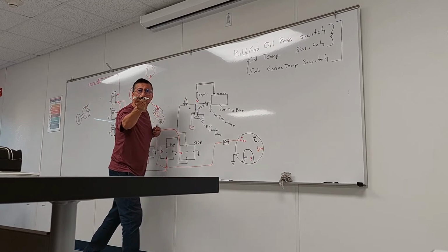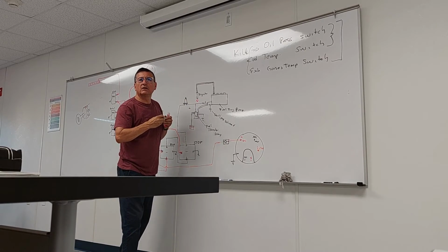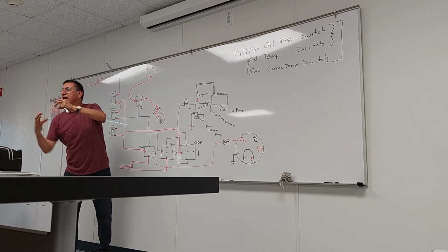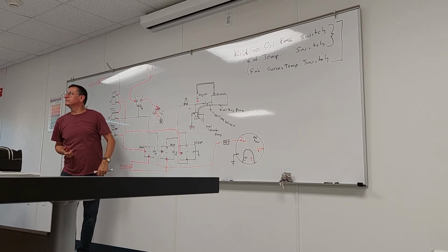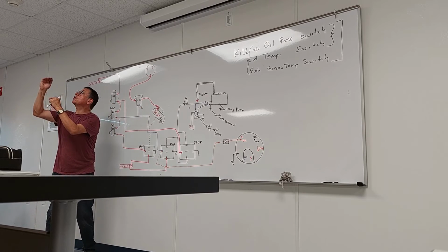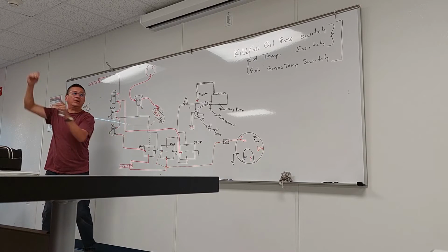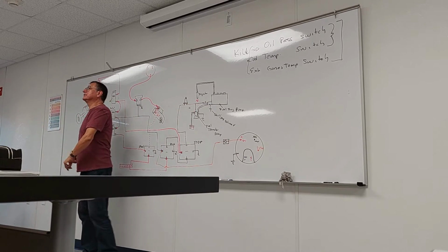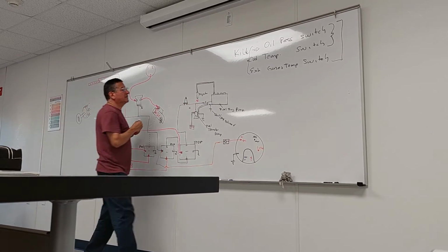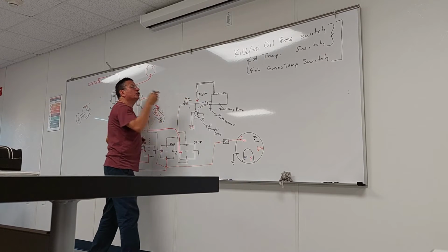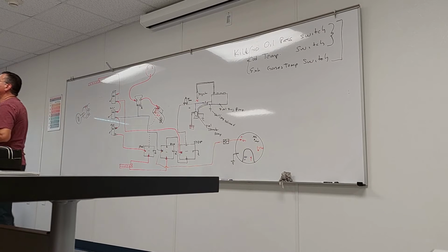That thread enters the bracket where the oil filter is located. If the pressure decreases below the limit or passes the upper limit, what happens? It interrupts the current for this and this. This is the oil pressure switch. Not the sensor, the switch.